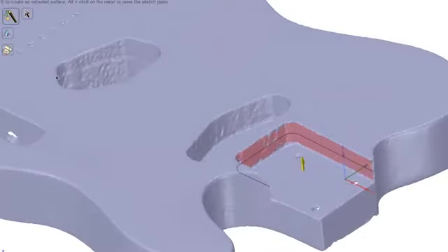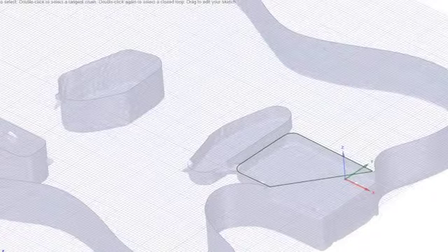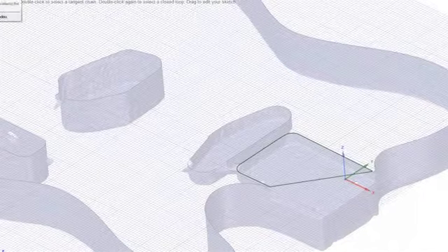I can go ahead and constrain that as I did before to the Z-axis. But this time I'm going to say only output a set of curves for me instead of giving me a solid. So I'm going to hit the complete box, and you see it jumps me right into a cross section of the mesh, and I'm in a sketch.